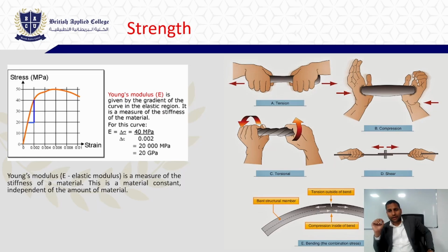He tried to understand what would be the behavior of steel under load. He tried an experiment and in that he applied a tensile load on the steel, and then he came up with the formula that modulus of elasticity, or Young's modulus of elasticity, is stress by strain. But in his experiment he applied only tension load, so that's why you need to remember it is tensile stress by strain. That is the only difference, otherwise everything is the same between Young's modulus and modulus of elasticity.